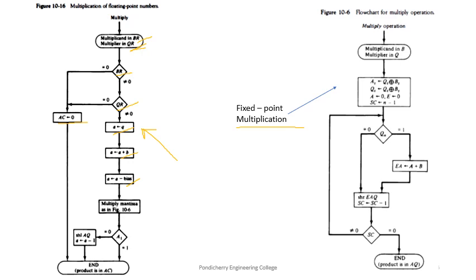So when you add the exponents a and b, a is also biased, b is also biased. Here the bias is getting added twice to the result, but it should be in biased exponent form, and only one bias is required. So this additional bias added due to the addition of a and b is compensated for, or removed, here. Then multiplication of mantissa.